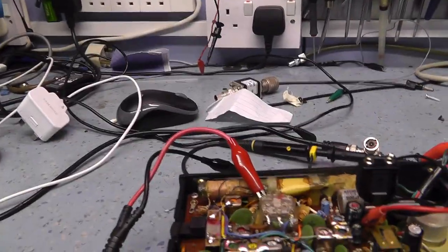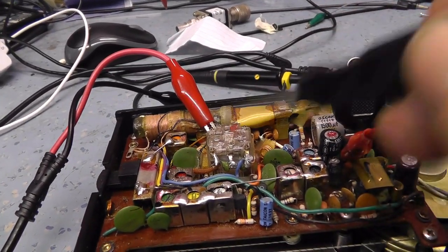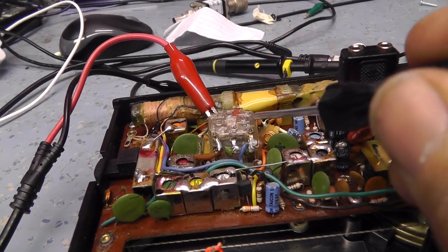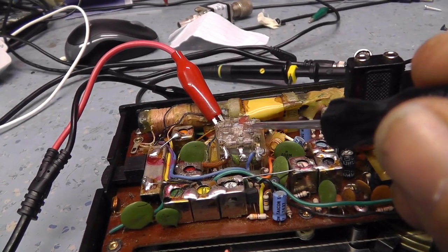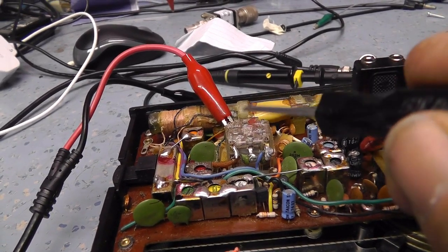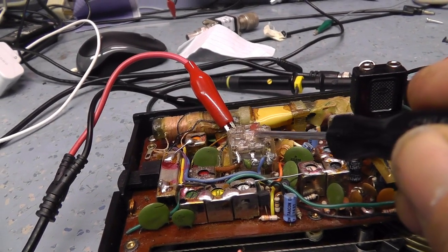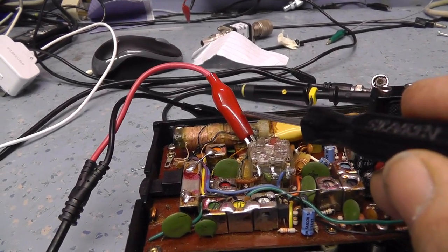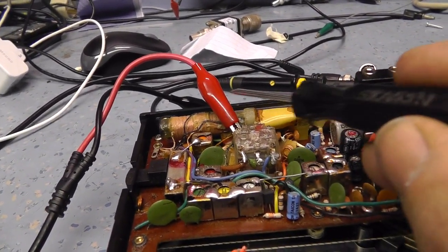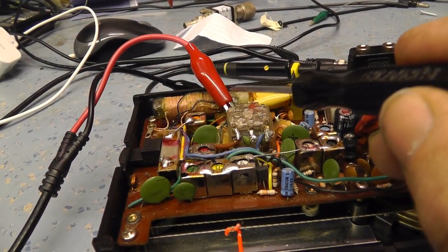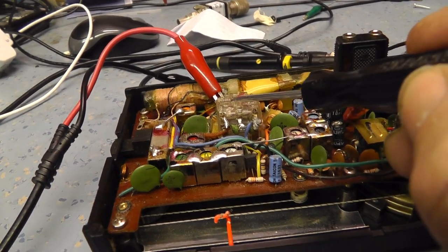So what I'm doing is I'm taking, this is the RF lead here, and all I'm doing is injecting that into the oscillator coil. Now, ideally you want to connect it directly to the IF amplifier, but the trouble with connecting anything directly to the IF amplifier, you're going to alter the matching of the IF amplifier. So what I'm doing is I'm putting the signal in before the IF amplifier, so I don't disturb any of the impedance or matching of the IF amplifier, and I'm feeding in a fairly strong signal into the RF section.